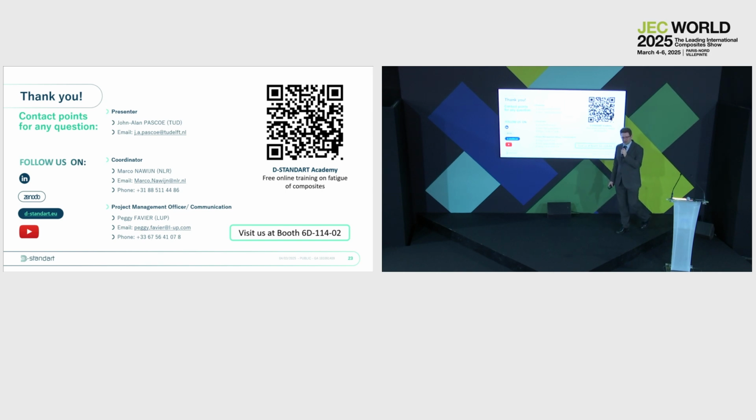Yeah, of course. So it's always a worry about the temperature increase. So the temperature is monitored during the test. What we've seen is that the temperature increase is relatively modest. So it's 10, 20 degrees, so not too bad. And additionally, we've also done this test at different temperatures so that we can then experimentally back out the temperature effect if there is a temperature increase.